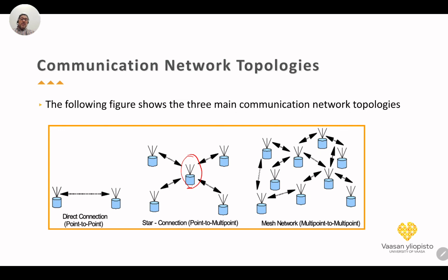For example, if sensor A wants to send a message to sensor B, and the coverage range is not enough to reach B directly, then it is possible to have it over different routes until B. Actually, sometimes even the power of A is enough to reach B, but we do prefer this multi-hop in order to reduce the consumed energy, as we will see later in this part.